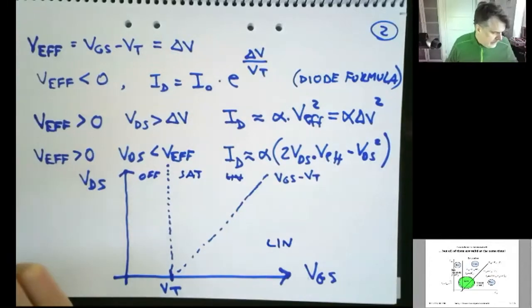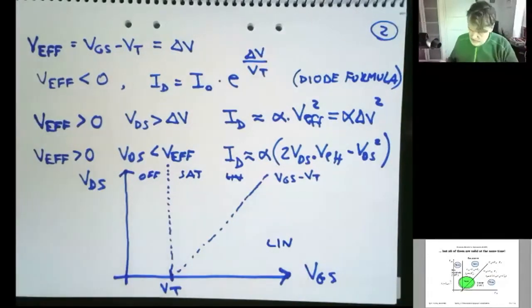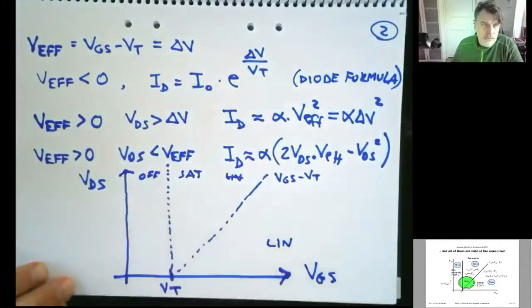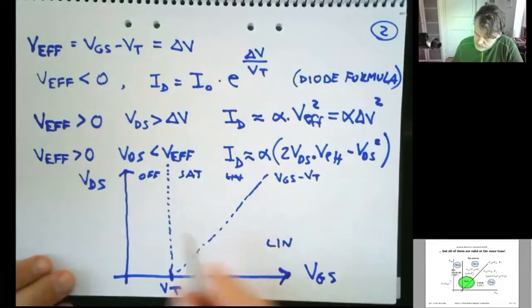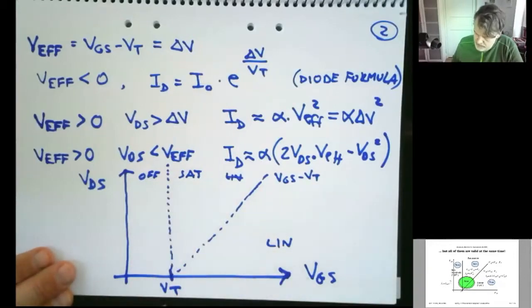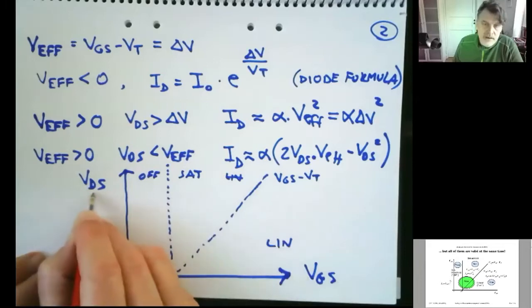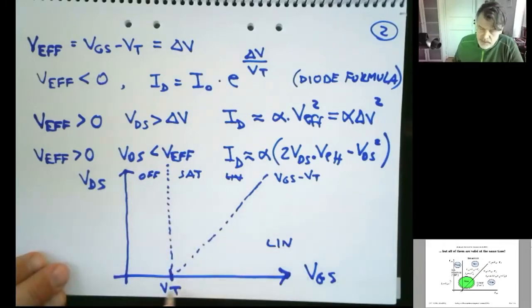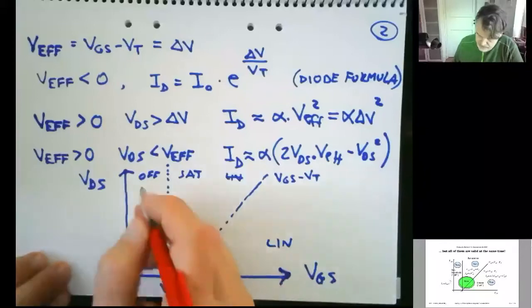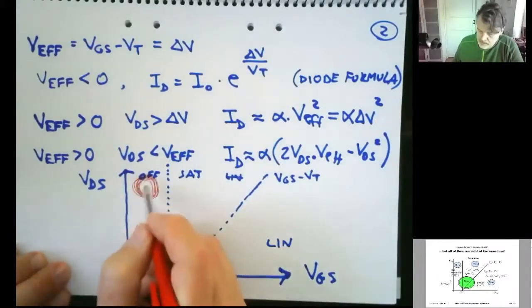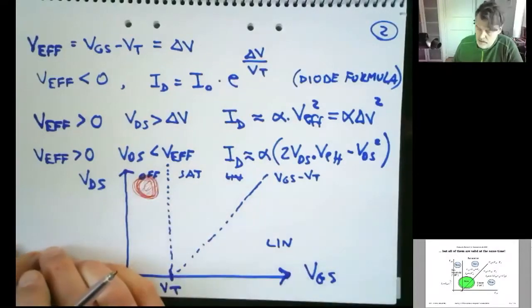And if you look at it, in the old days, when we used to have really high voltage, then VT was very small compared to the supply voltage or the voltage range available. And it was easy to design a very high voltage being distinctly far away from VT. So you could operate here in the old days, put your transistor really off.